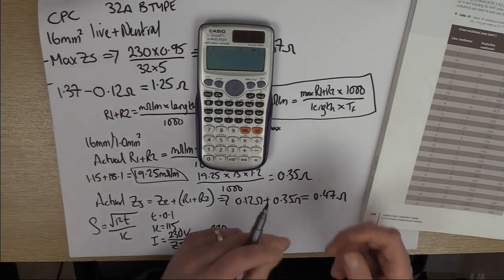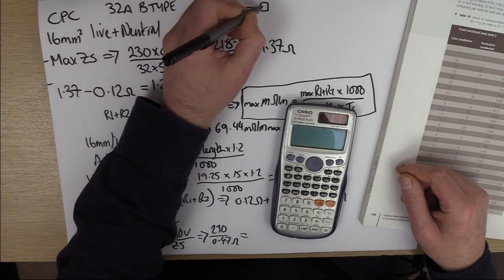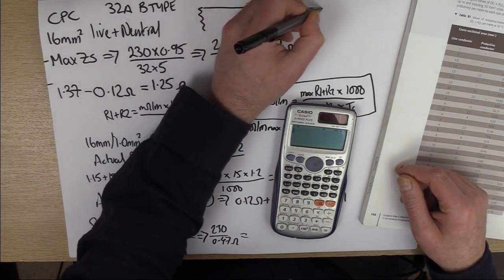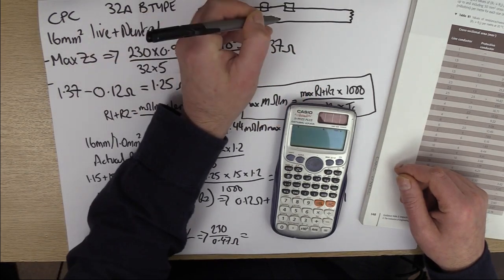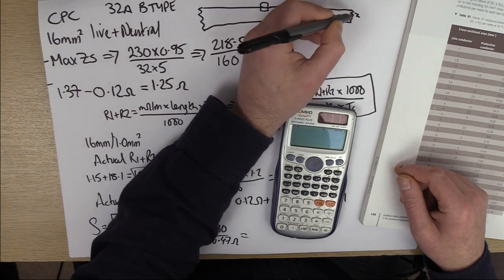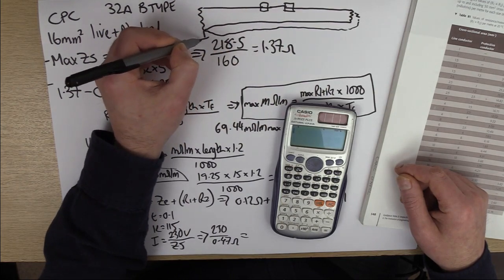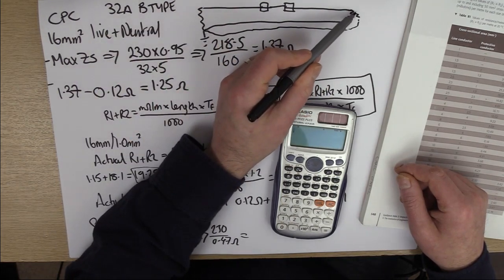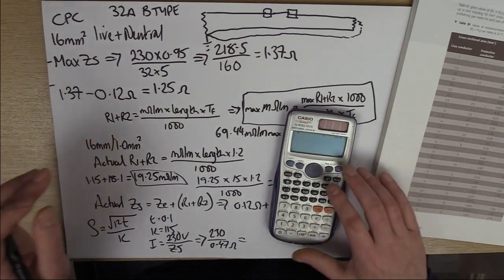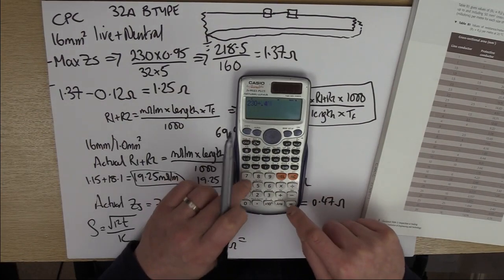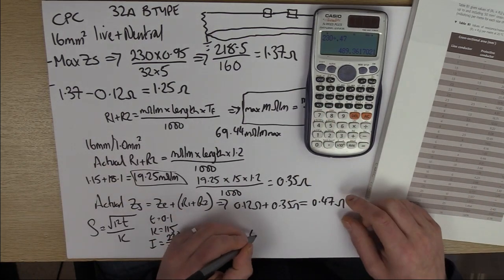So this is right at the end of the circuit, you know, substation, DNO's cut-out, breaker. Right at the end of the circuit, got our heater load, neutral coming back, then our CPC is kind of connected onto that. Let's say we've got TN-S. What we're saying is if the live touches the earth, this is how much fault current is going to flow. And it's telling us 489.4 amps.